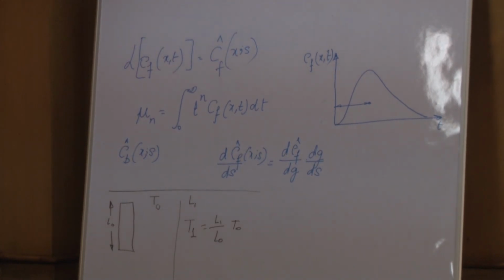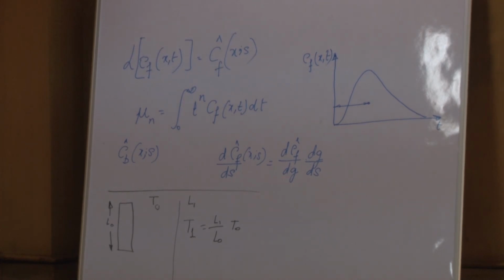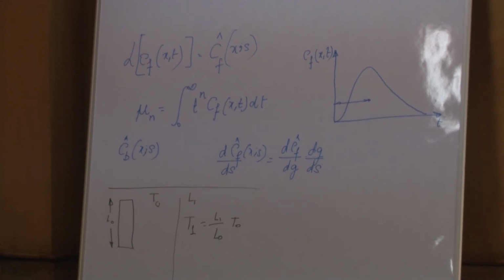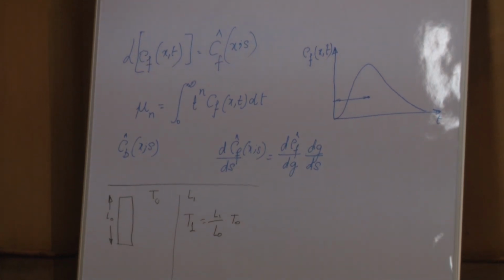descriptions. What we will talk about today is, we have talked about travel times, and again, like I said, we are anticipating. I'll talk about travel distances, where instead of the flux concentration, we will be using either the bulk concentration or the resident concentration along the column. That allows us to analyze it in an Eulerian sense.